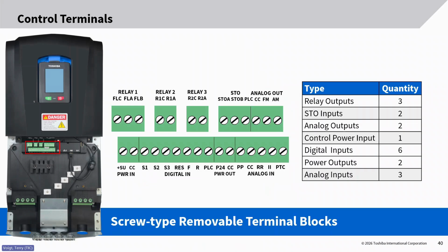So we have relays, those are full contact relays, an STO, so a safe torque off circuit. We have our analog outputs, our digital inputs, and some analog inputs as well. So very typical for a Toshiba drive. The same naming convention applies to all of those as well. So it should be very, very familiar to wire up an AS3 versus wiring up a WC1.